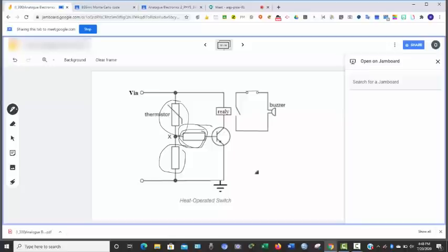a transistor and electronic device have what we call a data sheet, and in the data sheet you will have maybe the open circuit current, open circuit voltage, the base emitter voltage, and the base collector voltage. They will give you VCE, the collector emitter voltage. They will tell you the operation power. So with that, you can know what you are to design. They will tell us the HFE, which is also beta, to know what we are going to do and how we are going to model our equation.